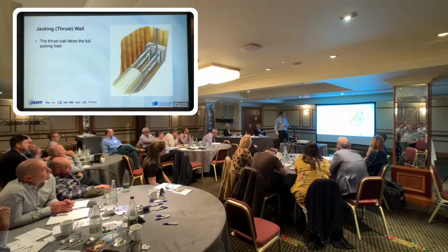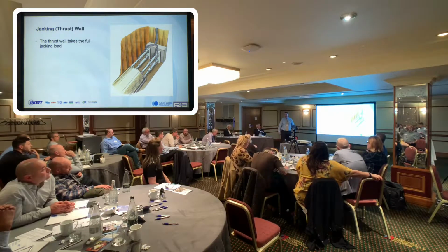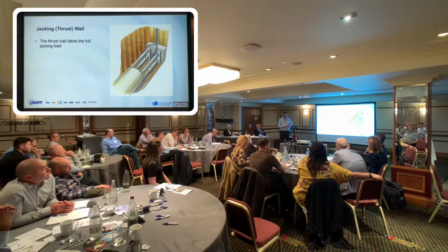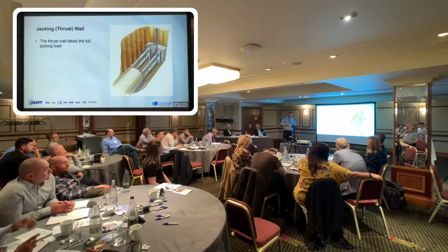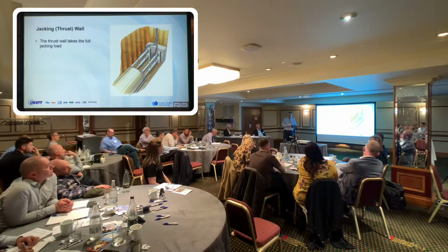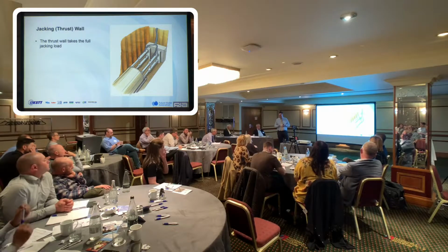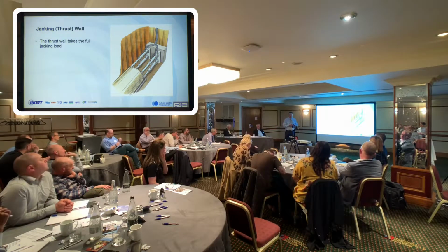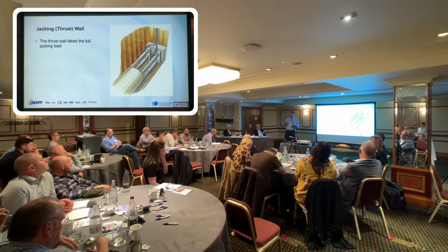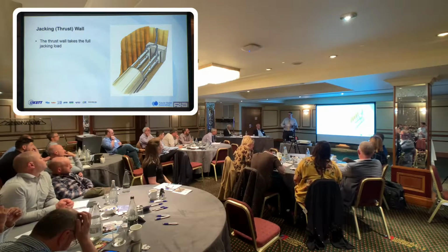So in terms of the thrust wall, it can take the full jacking load. Certainly when we design, we will look at the drive length, we'll undertake some estimations and look at the friction. And then for a 100 metre drive, we'd work out the maximum jacking load that we thought we were going to get. And we'd then compare that against the capacity of the pipes. And then that would allow us to work out whether or not we're going to need interjacks. As Graham said, I bow down to others in terms of the actual number, but certainly there'll come a point where even if you don't think you need an interjack, you put one in the line, probably just to be on the safe side, because of course once you've run out of steam, you've run out of steam.